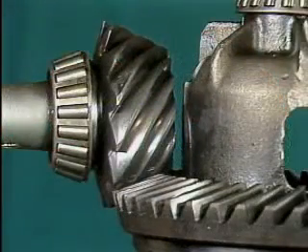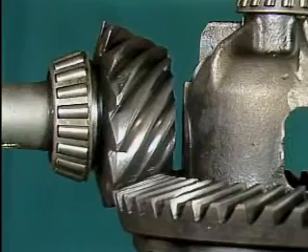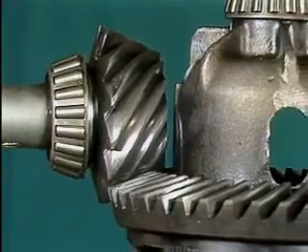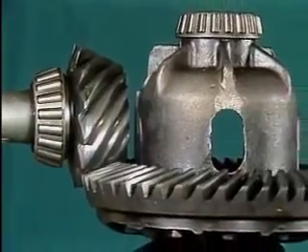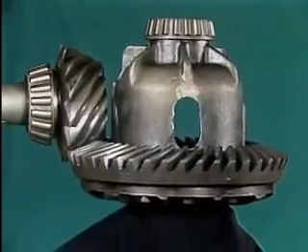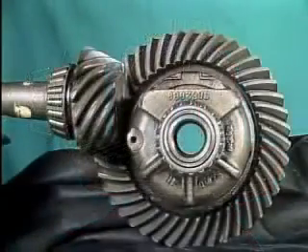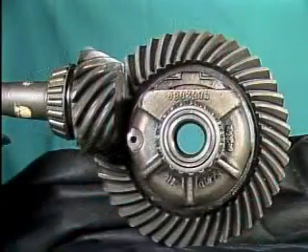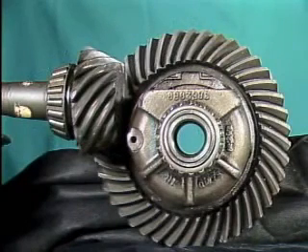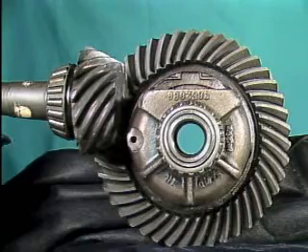This offset allows hypoid pinions to have as few as 5 teeth in a high-ratio gear set, while the various types of bevel gears typically don't have less than 10 teeth on a pinion. The smaller number of teeth on a hypoid pinion means that larger ratios can be obtained with a hypoid gear set than with a bevel gear set of the same dimensions.